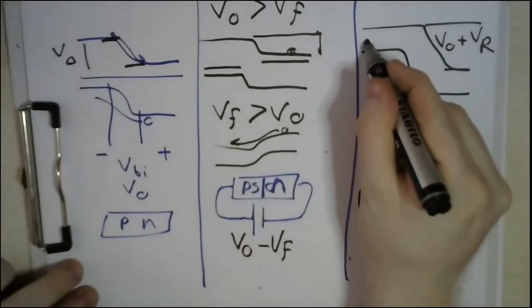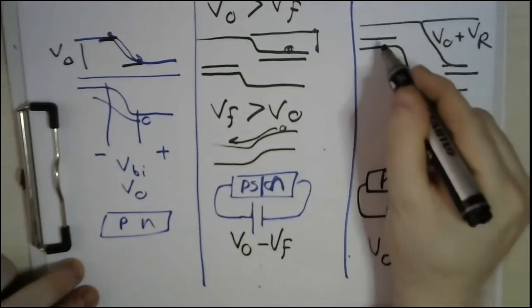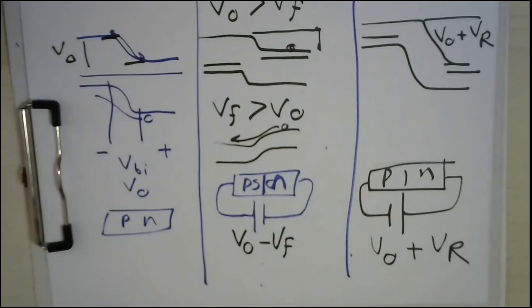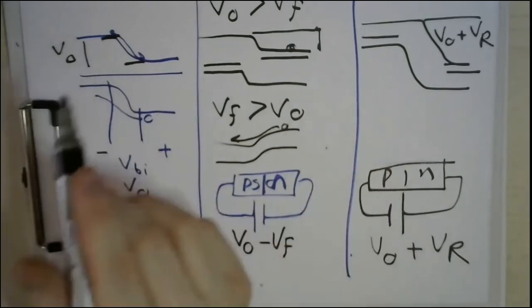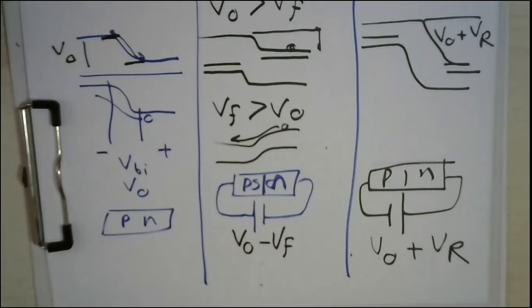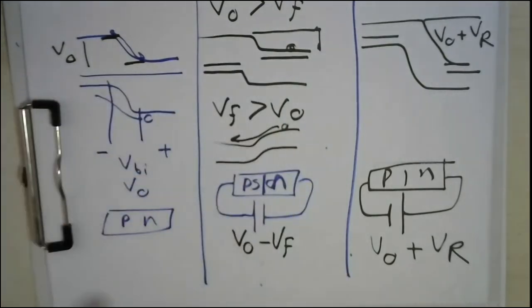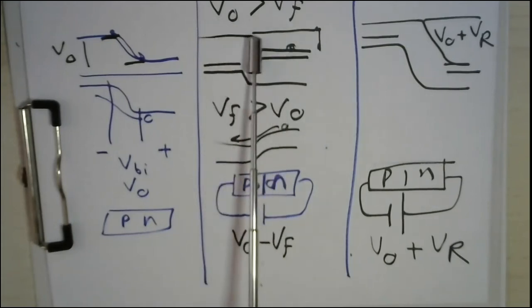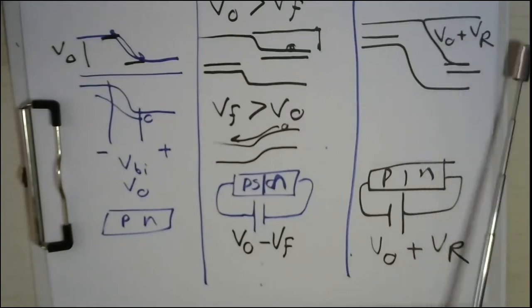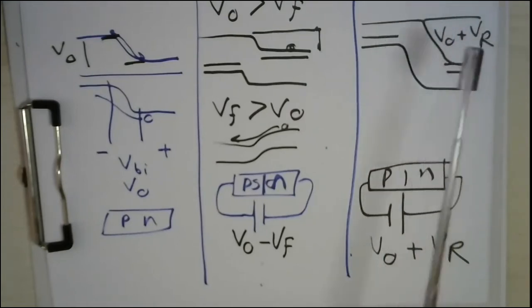Again, here the energy level is split and not a continuous energy level. So these are the different conditions for the energy band diagram. As you can see, you can adjust the height of your barrier based on your forward or reverse connection. Whenever you have a forward connection, your barrier starts to be reduced till it vanishes. Whenever you have a reverse connection, your barrier starts to increase.